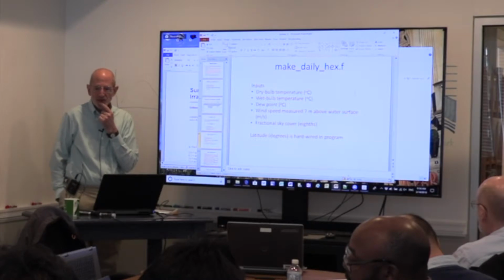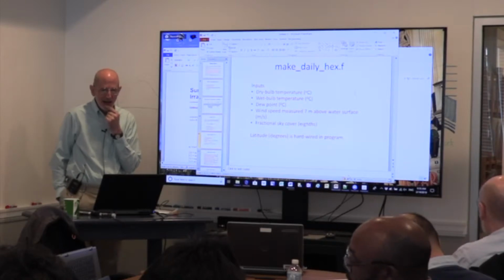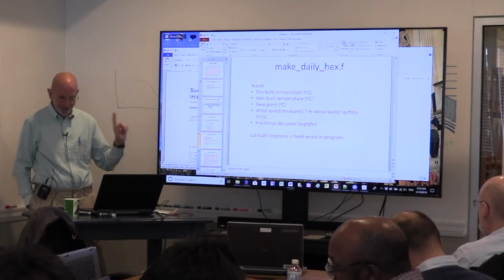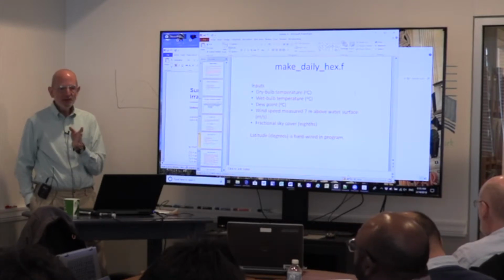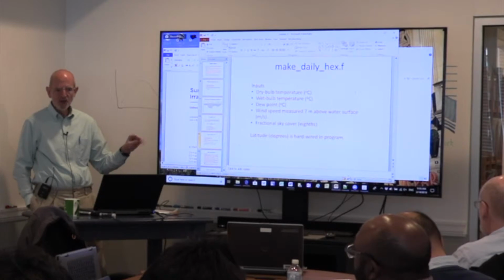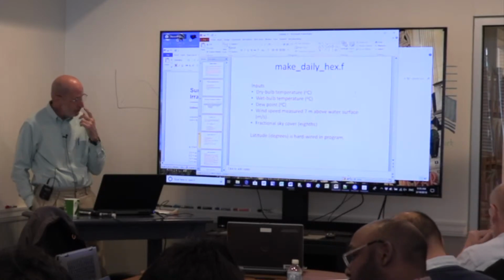So if you see fractional sky cover as 4, it's actually 50%, right? It's 4/8. And the program deals with this. But if you get it from a different source, and the fractional sky cover is reported as something else, like actual percents, beware. You want to go into the program and take appropriate measures.